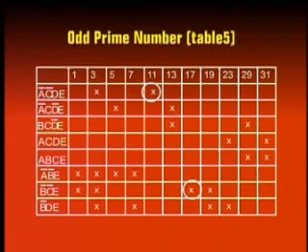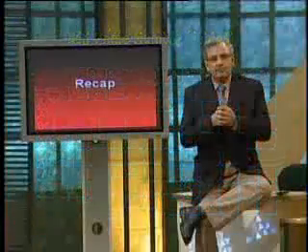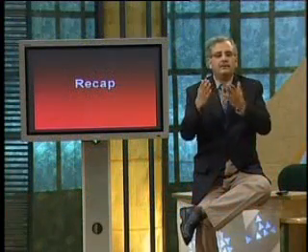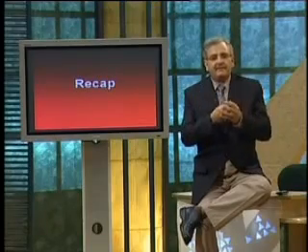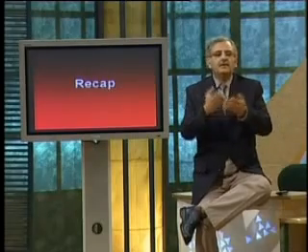Thus, the simplified expression that represents the odd prime number in the range 0 to 31 is represented by the product terms A bar, C bar, D, E; B, C, D bar, E; A, C, D, E; A bar, B bar, E; and B bar, C bar, E. We just looked at the expression derived for the odd prime number checker circuit. I hope the expression which we have derived here is the same as the expression which you derived using your program. Okay, let us start with the combinational logic.